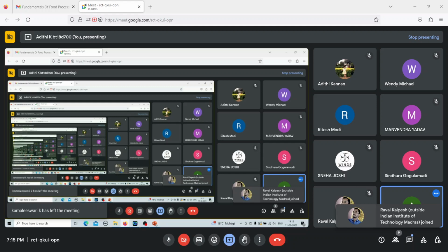It's very similar. When we use the concept of lethality factor, we calculated lethality factor at each and every time point. We summed it up and then we calculated the F0. Similar concept here, but we do not have delta t as constant. Suddenly we have 25 minutes here, we have 25 minutes here, we have 20 minutes here.